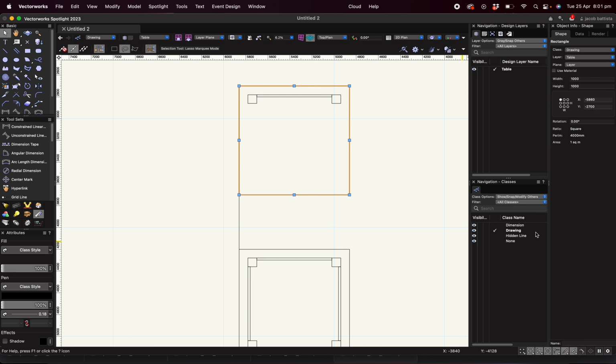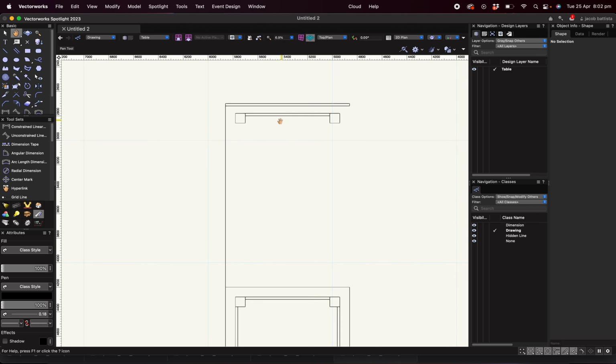So we know the table top is not that tall, or not that big now because we're looking at the sides, but it's going to remain being 1000 millimeters. The first thing I'm going to do is make it 20 instead of 1000, and that's going to edit itself using this as the anchor point. Using any of these top 3 anchor points on the 9 dots will keep that top line, or those top 3 dots, as the points that don't move. So if I click enter, it's going to straight away edit itself down to just being the thickness of the table.